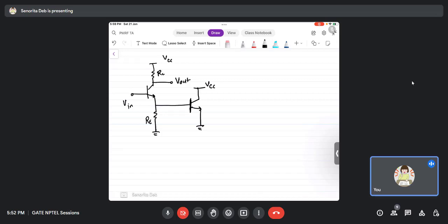So whenever this kind of question is there, see what this emitter resistance will actually see. What will this terminal see? This terminal is seeing one RE and another input of another BJT. So input of another BJT, what will it be? If it is a two-port network, suppose I don't have this BJT here. So now what I have is a black box. So what will actually matter? What will actually matter is what is the resistance, the impedance here with respect to ground, right?